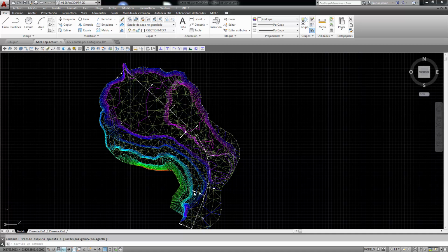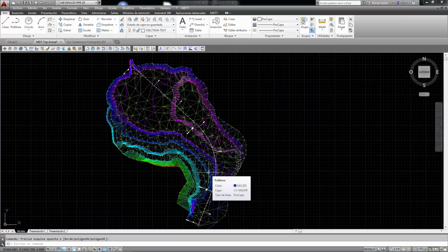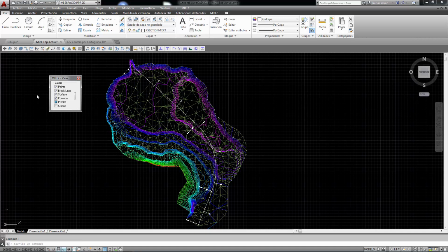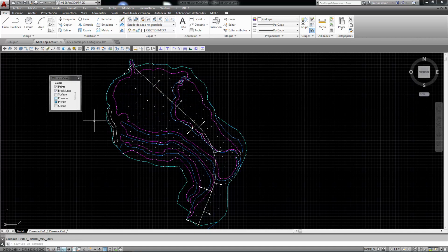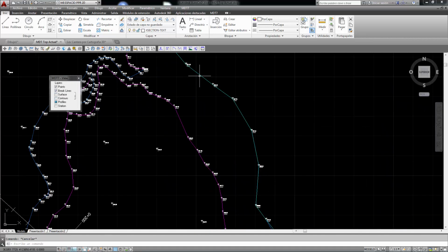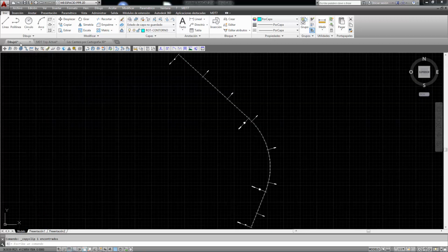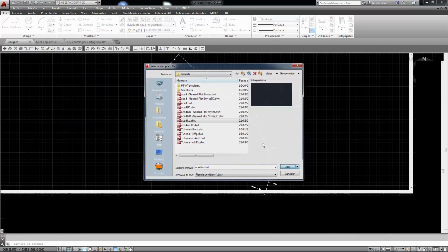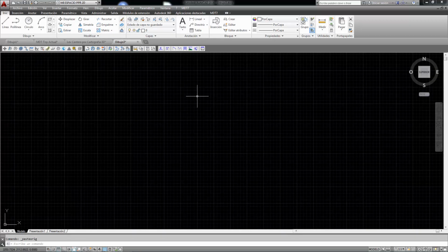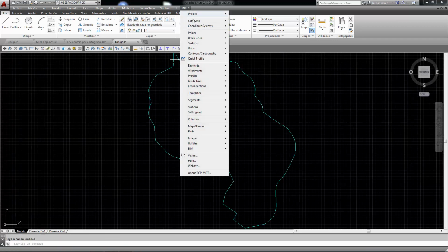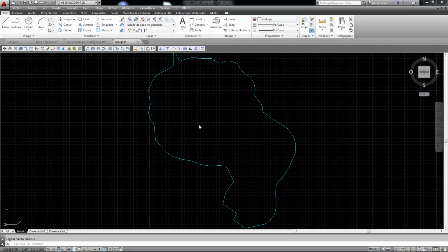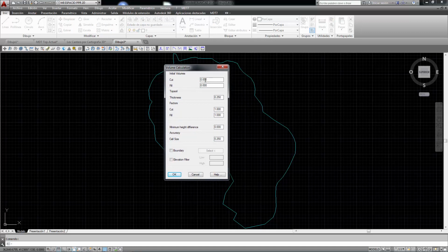Let us begin with our current worksite drawing under MDT Current Top, copying the contour line and pasting it in the original coordinates in a blank sketch. Our limits having been drawn, we now proceed to MDT Volumes Grid, or Surface Difference, in accordance with how we calculate the digital terrain model.